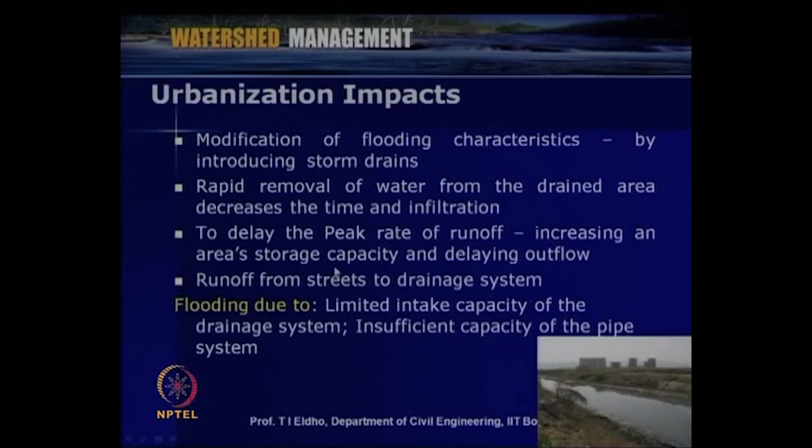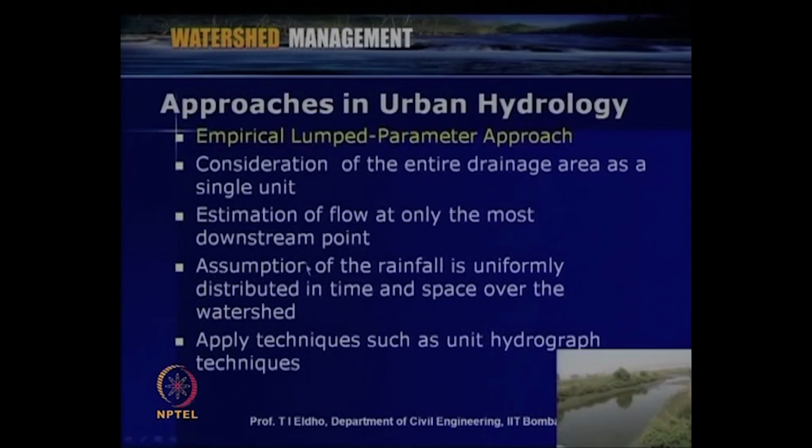We can add storage capacity and delay outflow, for example with detention ponds, so that this problem can be reduced. Runoff from streets goes directly into the drainage system, and flooding takes place due to the limited intake capacity of the drainage system and insufficient capacity of the piped drainage systems.